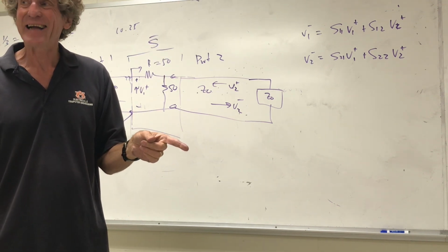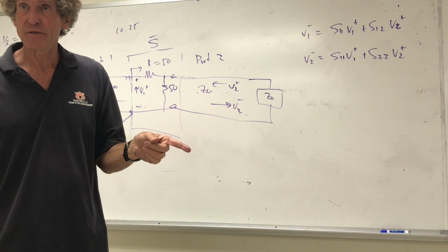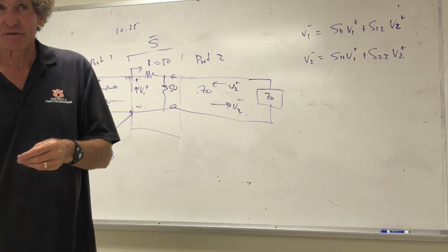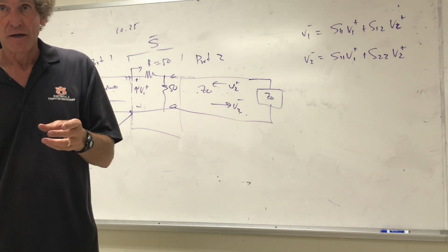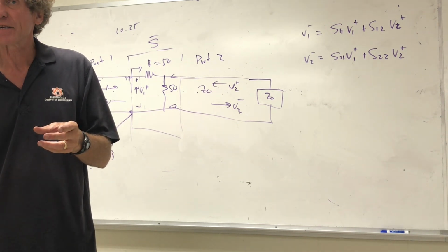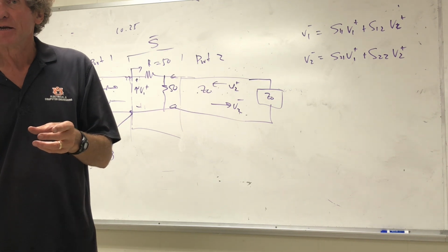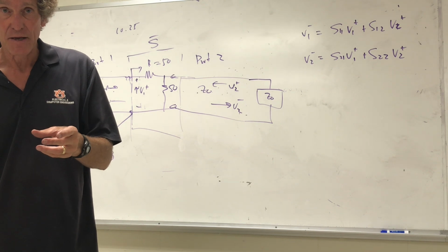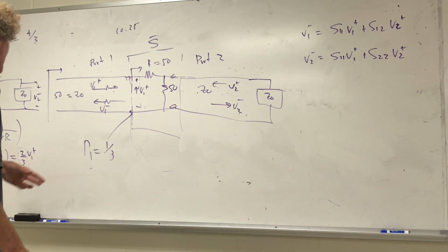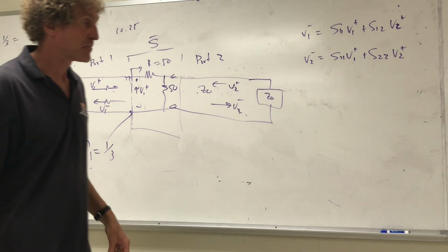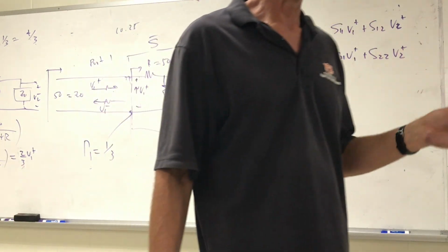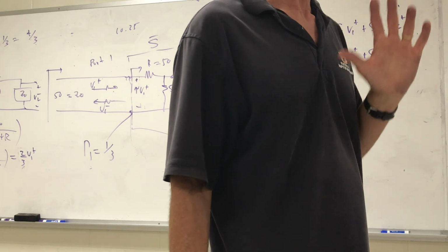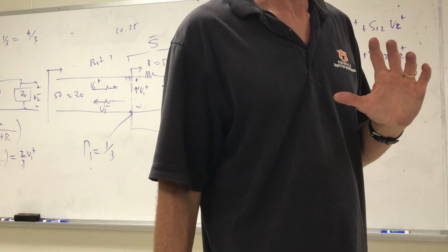So now that changes the input impedance, that changes the reflection coefficient. Transmission coefficient also changes, right? Now 1 plus the reflection coefficient is going to be what? 6/5. Do y'all follow me? So now that changes, and that will change the S22 parameter as well as S11 and S21. Please do those problems. They're laid out in the book.